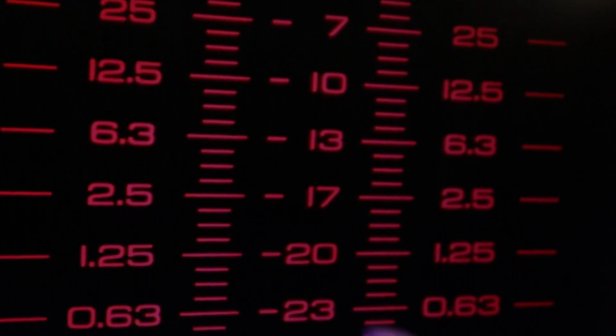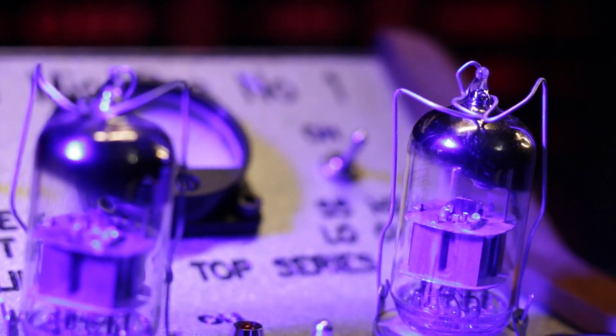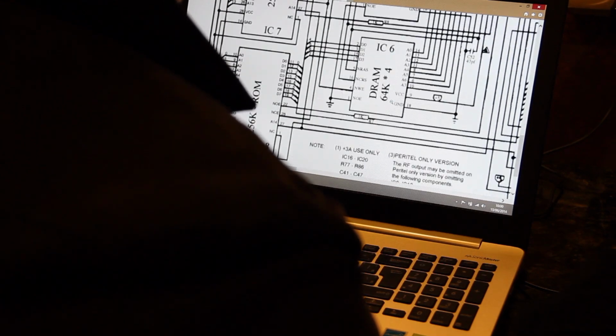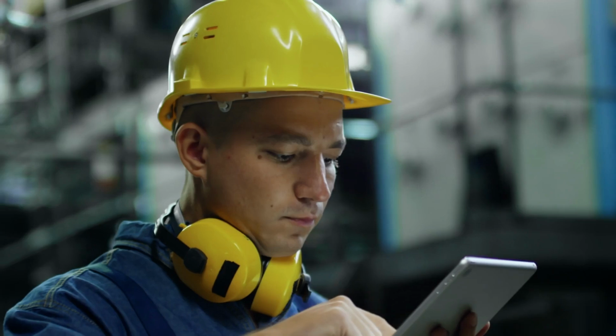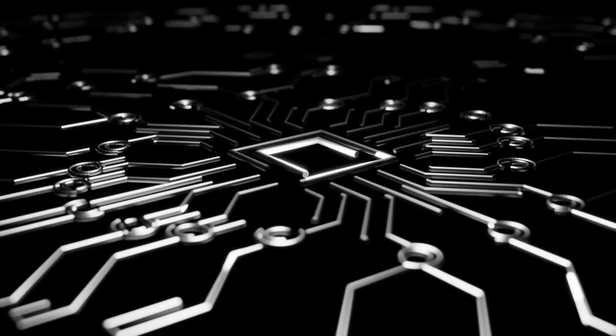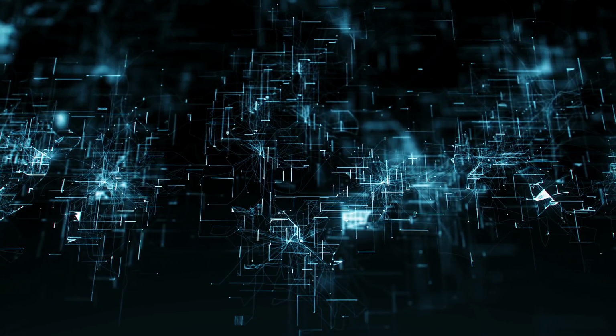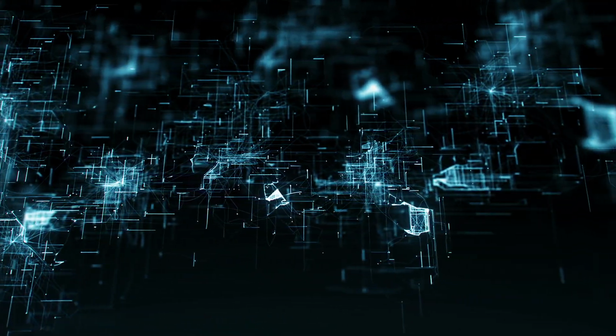Experiment 2. Diode, non-ohmic conductor. 1. Setup. Connect a diode to the circuit. 2. Measurement. Vary the voltage and measure the current. 3. Observation. Plot the voltage against the current. The result shows very little current until the threshold voltage is reached, after which the current increases rapidly.